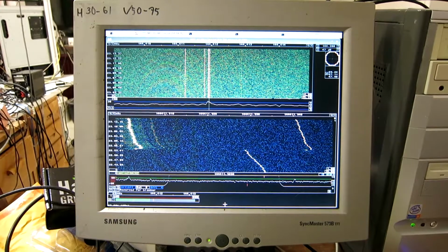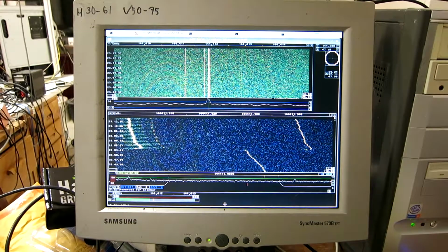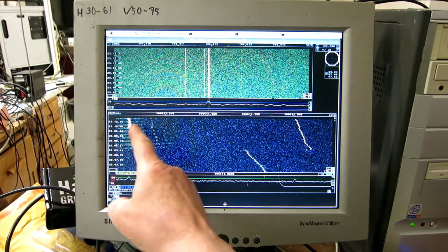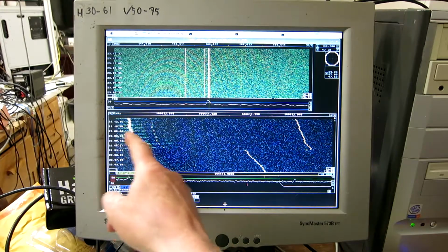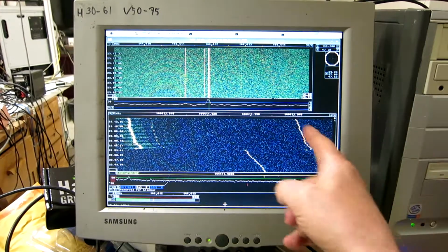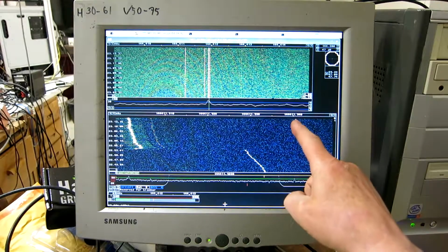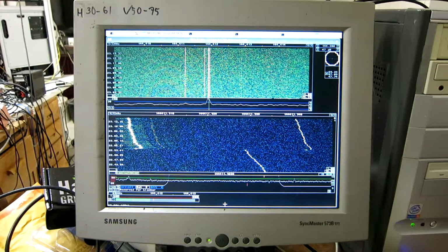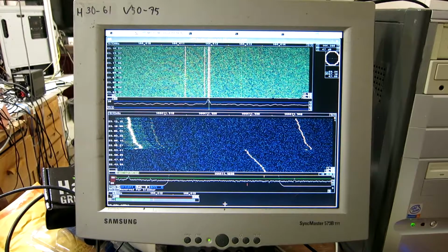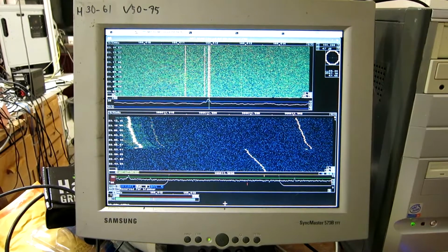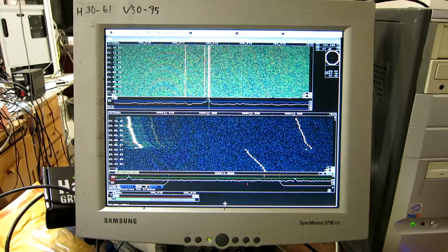Now the frequency scale is expanded and we have the beacon here with keying sidebands, and you see the keying here, and then my signal generator that is injected nominally 100 hertz above, but you can see it's about 40 hertz really. And now add 10 dB attenuation on the input here.